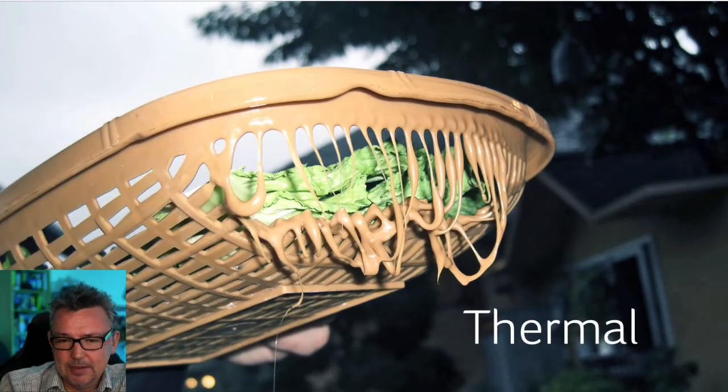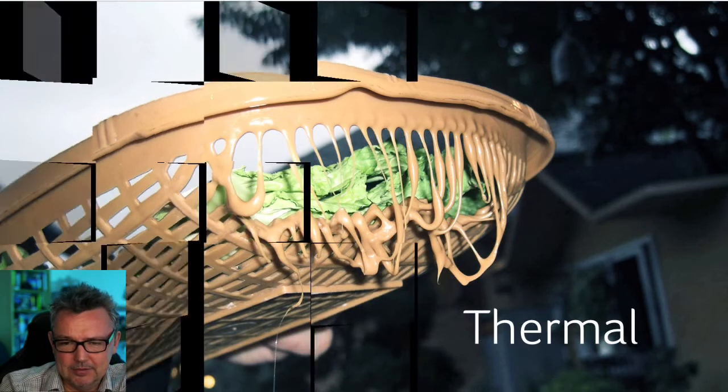Thermal bonding, so by heating up, either passing your web through between heated rollers which push it together, melt something that's meltable in there and basically bonds the web together. So you need at least some meltable fibres in a web if thermal bonding is going to be of particular use to you. They don't have to be all, but some of them do to help glue it together. Or you could blow hot air through, or just pass it through a normal conventional oven just to bond those together and give a bit of strength.